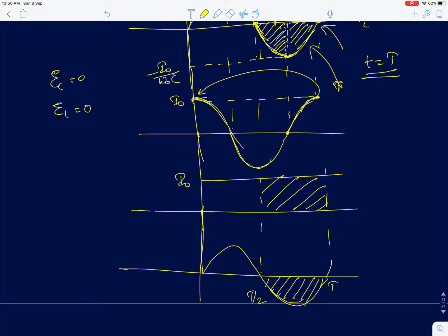When some element is absorbing power, it's going to dissipate energy. If I integrate in this half cycle, we can easily show that the energy dissipated will be 2L I naught square. At t equal to T by 2, the inductor had all the energy, and that was 2L I naught square. That will be fully dissipated by the current source at t equal to T. So that's what happens in a parallel LC circuit when you feed a step input. And this process continues indefinitely.